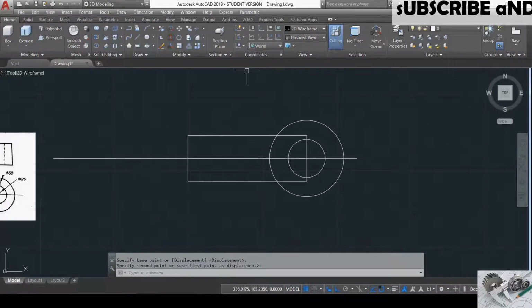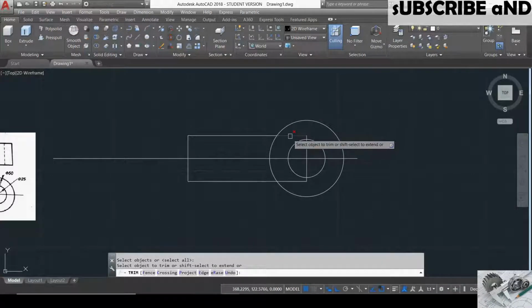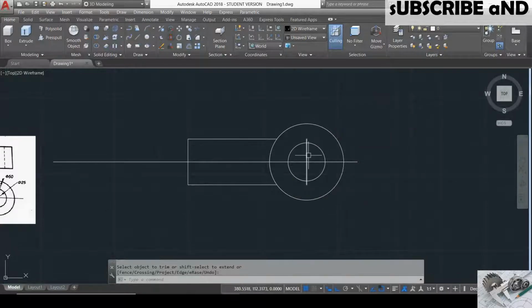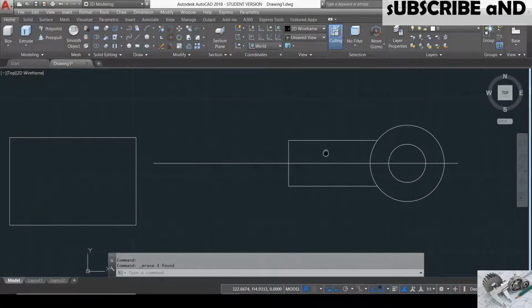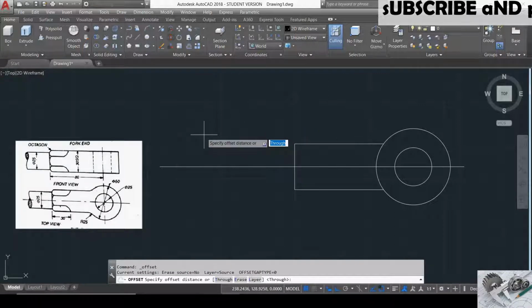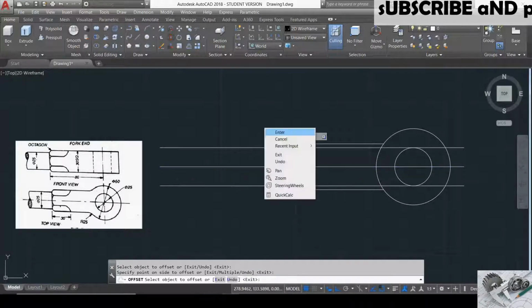Now we will trim the lines according to our requirement. The diameter of the shaft is 25 mm, so we'll offset the center line by 12.5 mm distance on both sides.